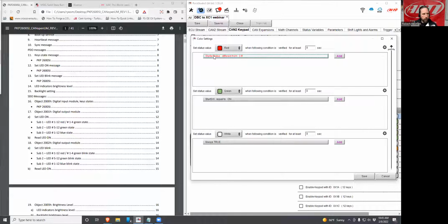So when this bit is on, you have a short circuit. When this bit is on, you're over temperature. When this bit is on, you are over current, or this bit is on, you're in an open load situation. So we don't have a ground. Tons of different things can actually trigger the one. If it's not a 0, you have a problem. Yes. Turn it red. So 0 is good. 0 is everything is working.